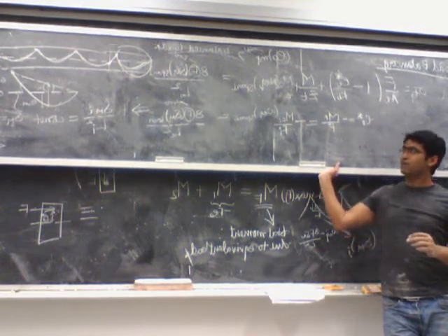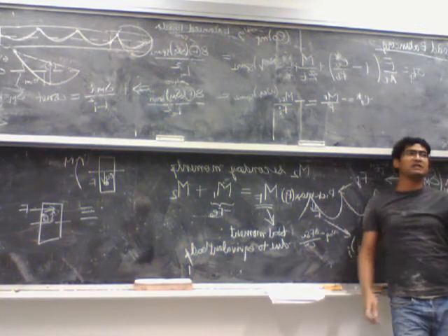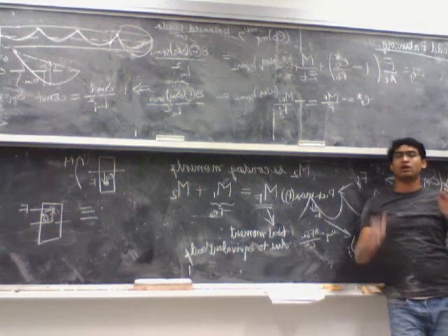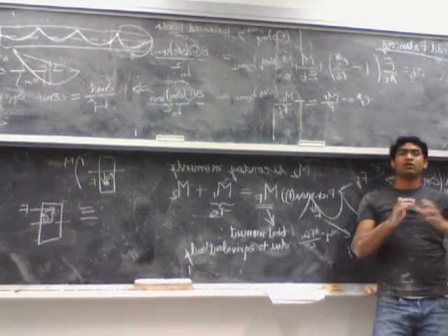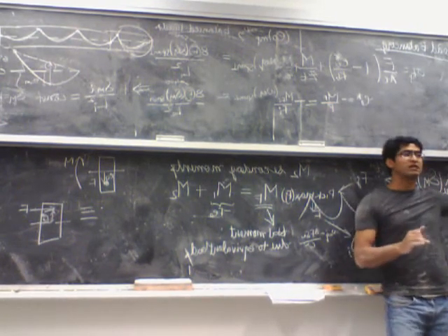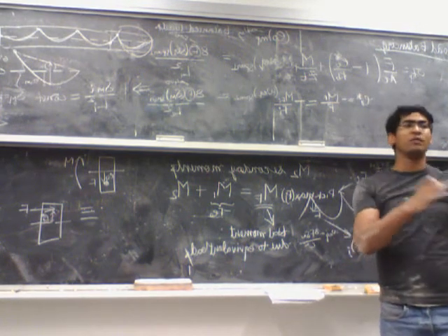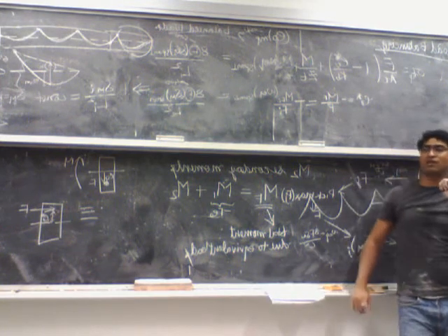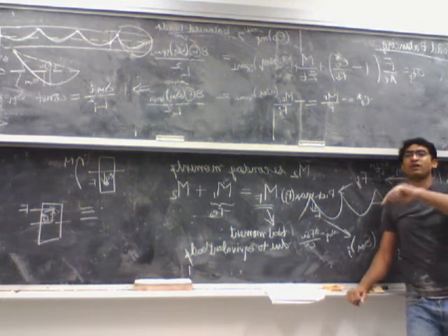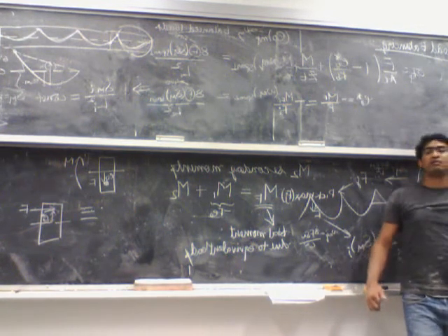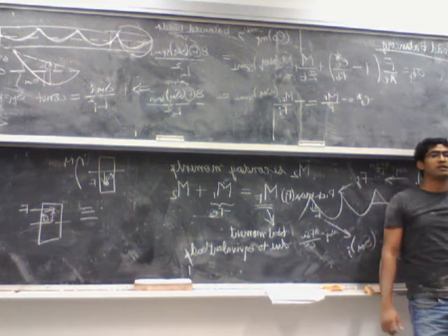So I think the biggest confusing part in case of a continuous beam is how to find out the pre-stressing force and the tendon profile. So what you do is you write down the equation for the equivalent loads which needs to be balanced. You maximize the delta M for each one of the spans individually. You will get 10 or 20 values of F depending on how many spans you have. You pick the largest value of F. You go back, you use the same equation, but now you know the value of F, you calculate the value of delta M, and then based on the tendon profile, you can relate your delta M to the eccentricities at the midspan.